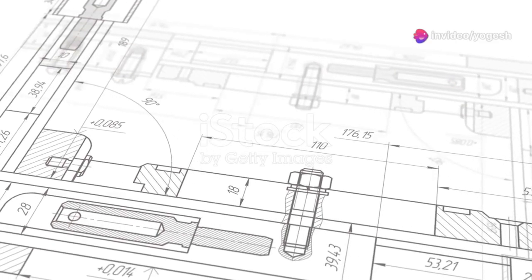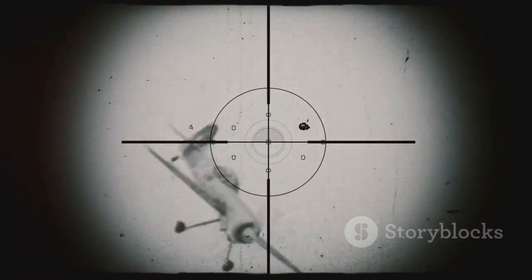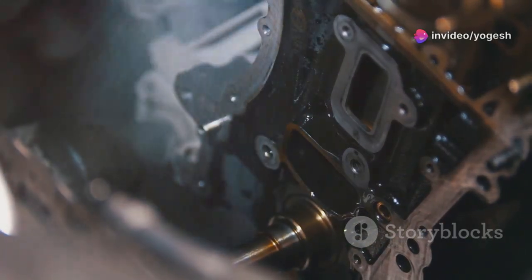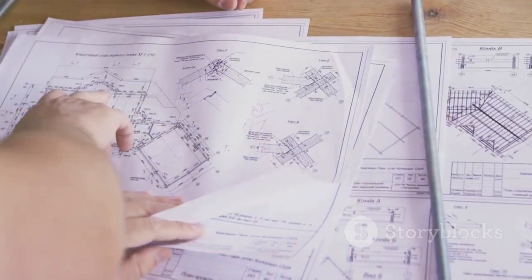Datum targets come in 3 types: points, lines, and areas, each with its own symbol and use. Datum target points are single contact spots, shown as a crosshair symbol. 3 points define a stable plane. Datum target lines are straight contact lines, ideal for cylindrical or elongated features, depicted as a phantom line with a special symbol.